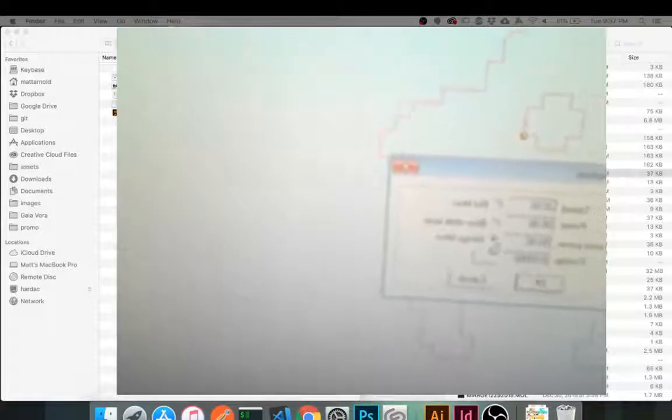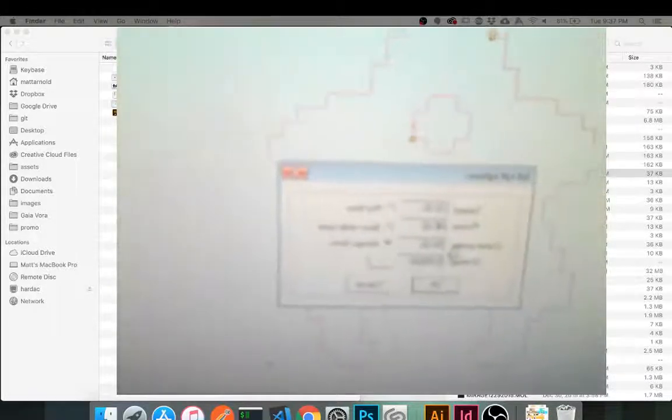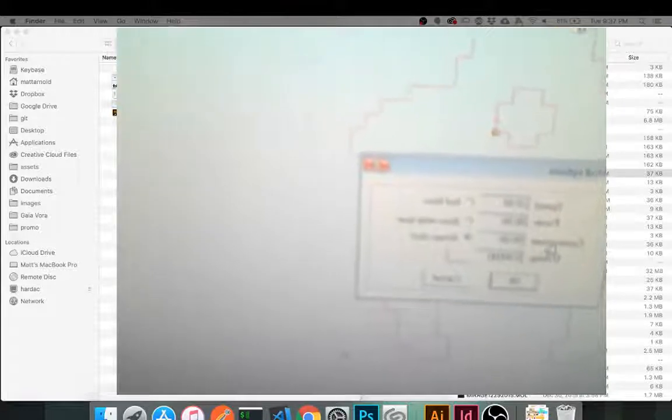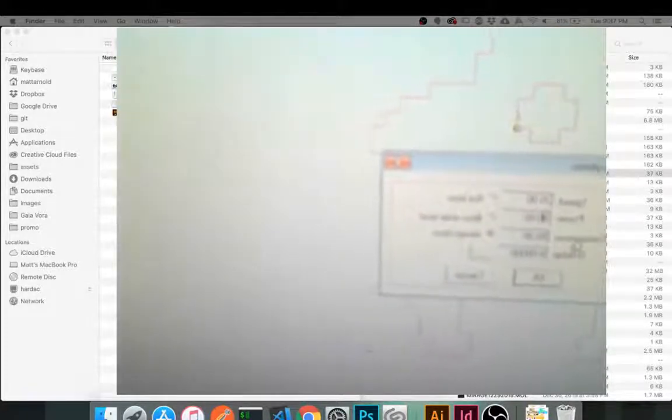Now, corner power is interesting. So here's corner power. In a piece like this, I wouldn't be too concerned. But what corner power is, is that this gantry with all of its belts will cause the laser tool to zoom along a path, and then it hits a corner, and it has to slow down into that corner so that it can make a really sharp turn.